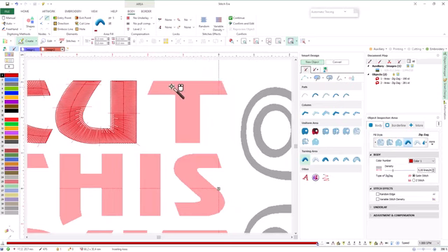A shape like this would usually be digitized using 2 objects so that the stitches in this region are vertical and the stitches in this region are horizontal. However, we can digitize it with only 1 object, using auto trace and a geometric element that we have not yet mentioned, cut lines. We capture the main outline.